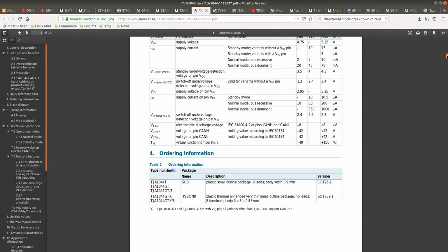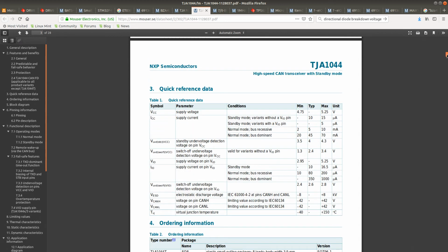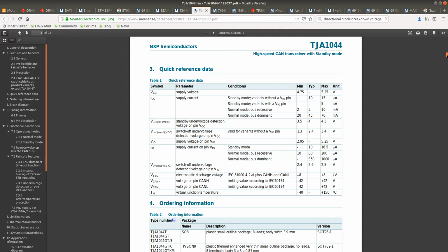So ideally, it would be better to use something that goes beyond 48 volts when we have a 48 volt system. This is not really that important, because this is just to protect, to make it kind of foolproof. If you have a 48 volt system, somebody may just plug 48 volts into any input on your device, and then things can break or things can short.